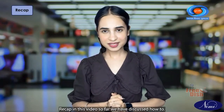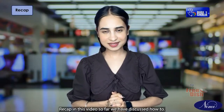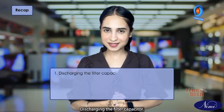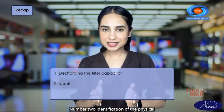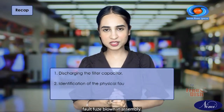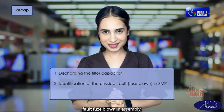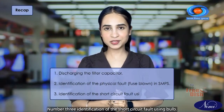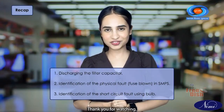Recap. In this video, so far we have discussed how to: number 1, discharge the filter capacitor; number 2, identify the physical fault, fuse blown in SMPS; number 3, identify the short circuit fault using a bulb. Thank you for watching.